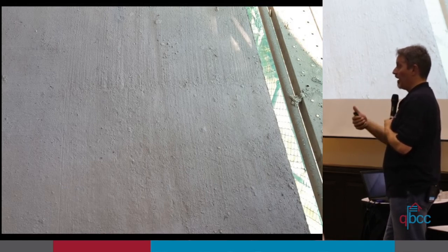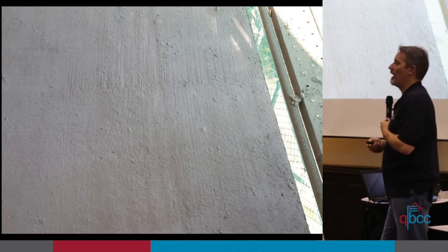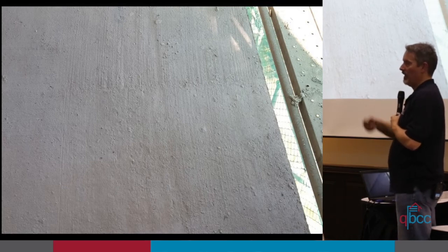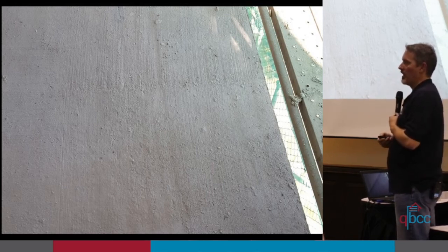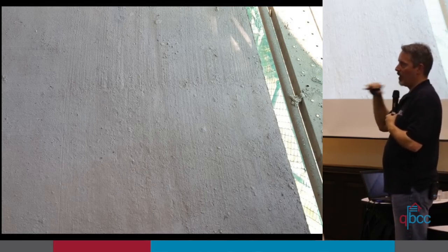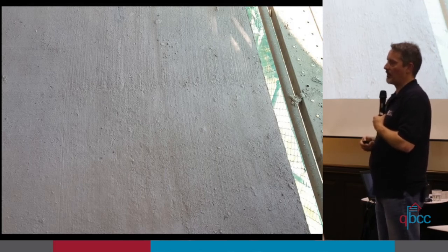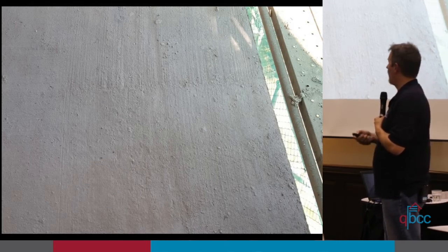So wood float, very, very light broom finish, single pass of a helicopter. But definitely you've seen in the surface profiles, your steel floated water wiped concrete doesn't even appear in the scaling because the Concrete Institute doesn't believe that water wiped steel floated concrete, it's really only good for a warehouse floor. That's about it. It's no good for any following surfaces.